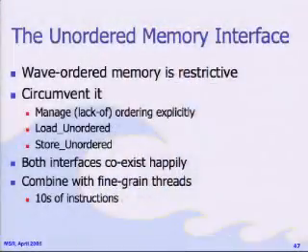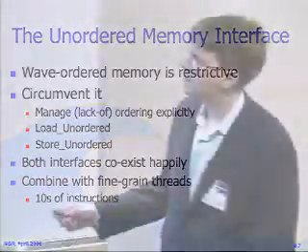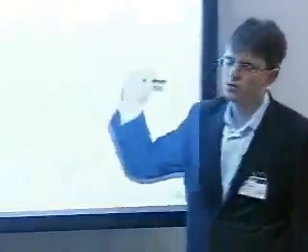One nice thing about, in addition to prefetching, another thing that we can do is that because the WaveScalar execution model is very latency tolerant, it's pretty easy to imagine building kind of super WaveScalar processors by taking multiple cores and stamping them out and connecting them to one another. So that execution model still works fine, and so we can use that to buy more capacity. There's some other techniques that I can talk to you about offline that we've looked at for solving this problem also. Okay. I'm going to talk next about some of the features of the underlying data flow.